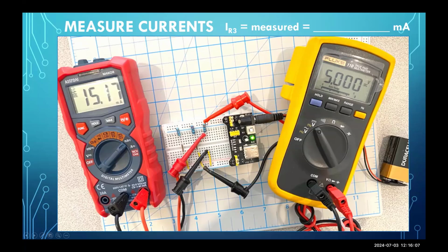Voltage is still 5 volts, and notice my connection points are slightly different. The red hook is still on the voltmeter on the positive side of R3, whereas the black wire is somewhere on the blue rail. It doesn't matter where on the blue rail it is. Remember, everything on the blue rail is one common point, connected with nothing but wires, so it makes no difference for my voltmeter where I hook up the black hook. It's a happy camper showing us we've got a solid 5 volts.